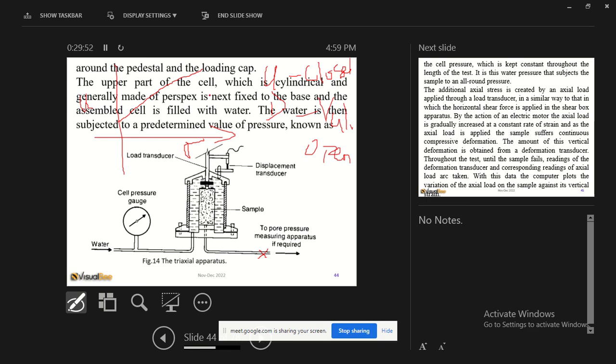If you increase the stress, the pore water will just increase. So this is the undrained condition. The drained condition means you increase sigma, and excess pore water can flow away, so the pore water remains constant because the valve is open. So please note that drainage condition.